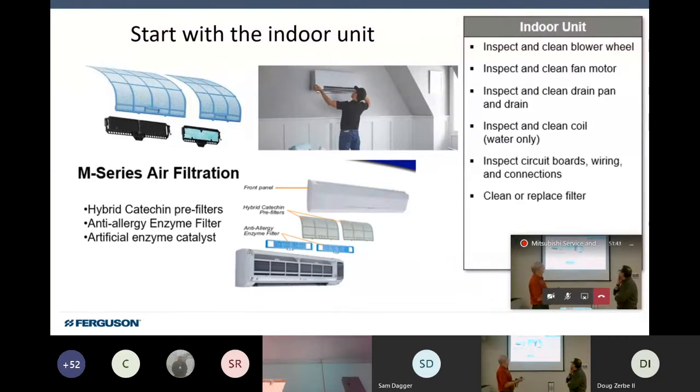Inspect and clean the drain pan. We'll show you part of that. Inspect and clean the coil, water only. That's Mitsubishi's statement. The reason they say that is they don't want anything eating into their coils. There is a small coating on Mitsubishi's coils. We cannot use harsh cleansers at all.